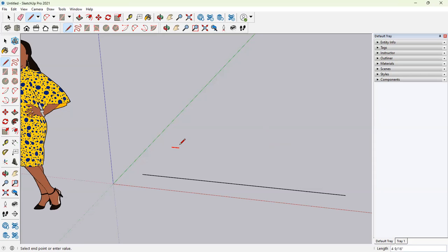So now let's say that you want to draw a line that is 2 meters long. If you have noticed, on your right-hand side, there is this measurement toolbar, which is giving the length. If I escape from the tool, it will just say measurement. You cannot type in here. This is how SketchUp reads your commands, directly through the typing that you're doing on your screen.